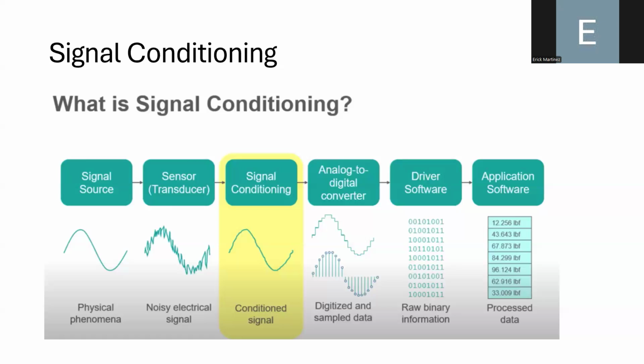Then we can transfer that information into a computer by using an analog to digital converter. The idea here is that we are taking samples at a certain time interval of the signal that we want to measure. In this way we are discretizing the signal, and those discrete values, which are basically performed in steps, are converted into a binary representation that can be read by a computer.